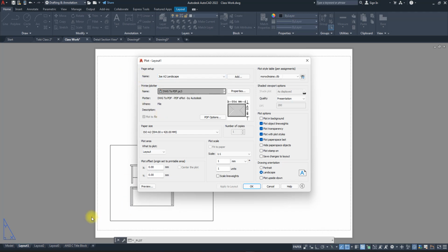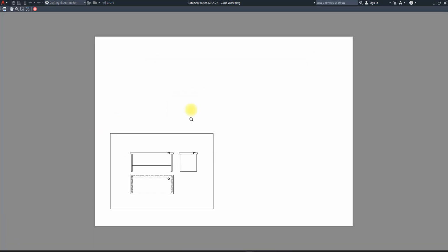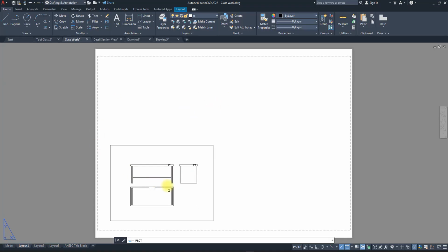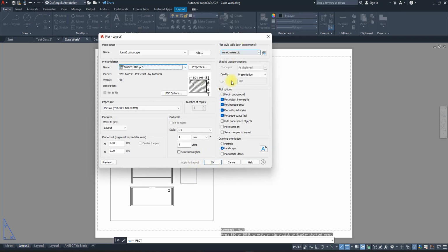You notice in that layout, that is more of a setting layout, but here you want to do the final print. So you can now choose a particular page setup. Whatever setup you choose here, all these things will gray out because you've already set them. You can just preview and see how it's going to look. Then from here you can start setting your page and just print out.